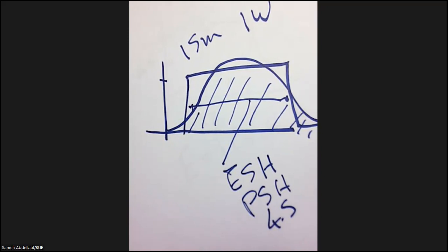So in this case, you can make a very easy and rough estimation for your energy production of a PV module just by one click. For example, when you buy a PV module in Egypt of 100 watts, the average of peak sun hours in Egypt is 5 hours, then the estimated energy to be produced per day in Egypt will be 500 watt hour per day.